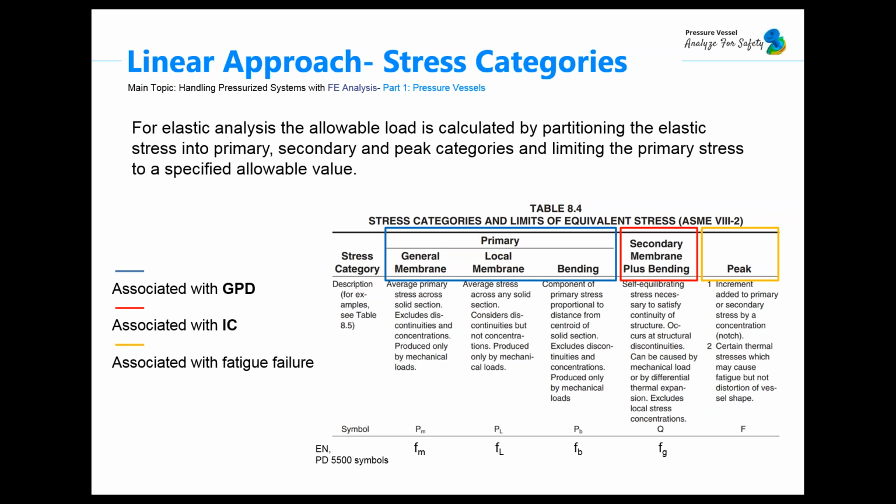Different stresses have different degrees of importance, and this is why they have been categorized in the code. Once again, we are talking about the elastic approach, and what we want to do is perform categorization of the stress. Before that, it has to be understood what the loads are which will act on the geometry. There are several different load cases that need to be analyzed, taking into account different scenarios during the lifetime of the vessel. Usually 2 cases are analyzed: design loads and operating loads.